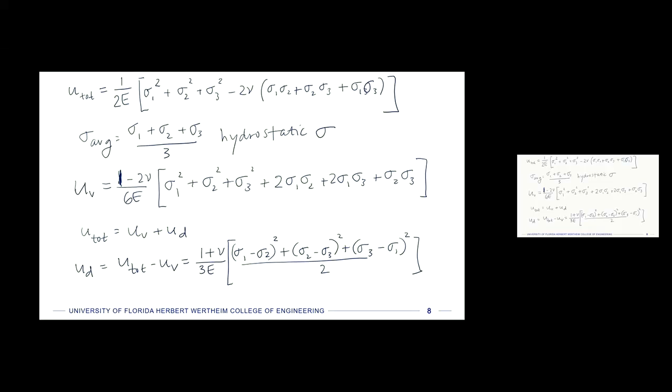So we have to get a failure criterion. We're going to apply this to a uniaxial tension test, see when that would yield, and then come back and see how these combine in order to get to that case. It's the same for the other yield criterion.